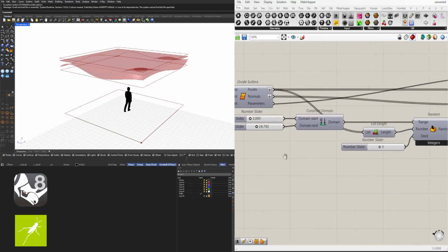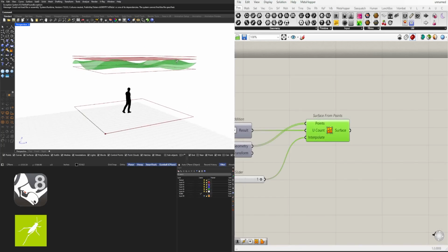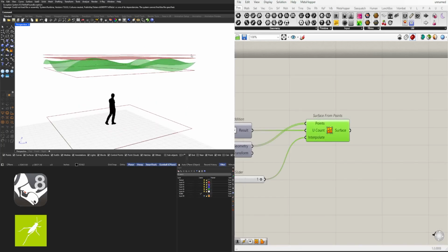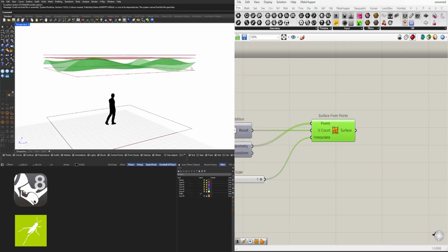All right, so for the next step, what we need to do is turn this into a solid by starting here at the top and then using this as the bottom face. So what we'll do here is project the outside line segment to the top.